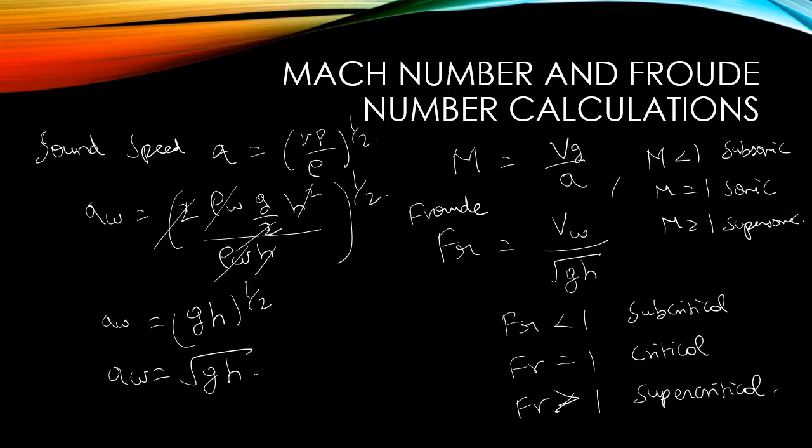supercritical flow. So the subcritical flow is used for surface water waves, that is surface free waves, okay, that is for subsonic problems. And for the critical case we go for transonic flow problems. And for supercritical waves, we are considering shock waves. So your hydraulic analogy will become a hydraulic jump, which we will see next.